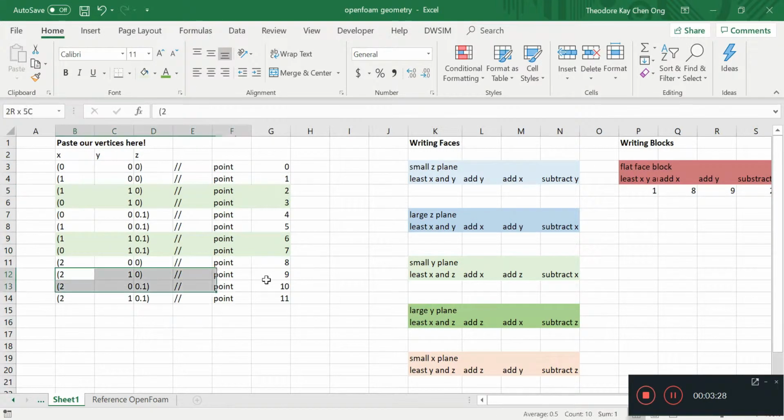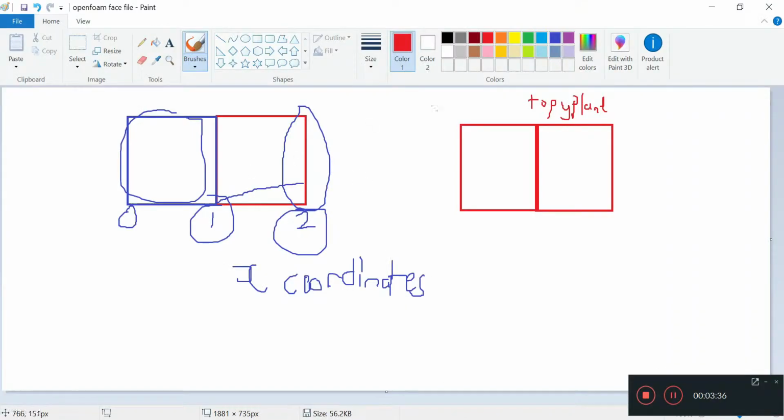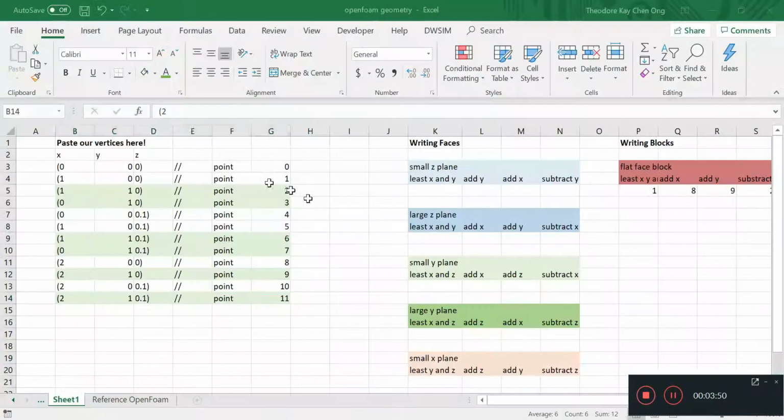Now we want to have all the y coordinates equal to 1 highlighted, so that we can define the other face, not just for this part, but for this part. So 3, 7, 6, and 2 is for this part. This one's x equals 0, this one's x equals 1, and we've got an x equals 2. If you notice, points 3, 7, 6 and 2 all have x equals 1 or 0.